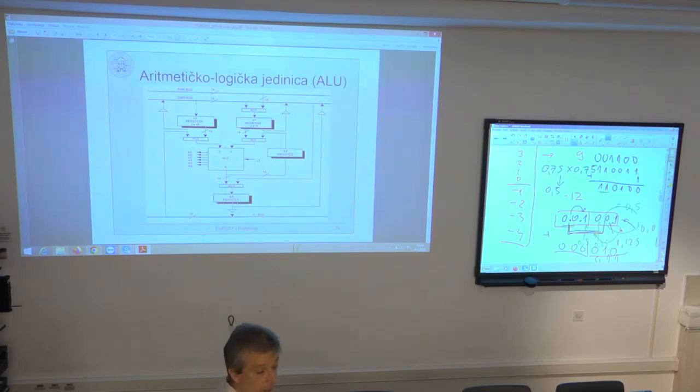So when you have the stack, another interrupt can interrupt the current interrupt service routine that is being processed, like a nesting of the interrupt requests. This cannot occur here because you only have one set of shadowing registers. So immediately, as you enter the interrupt service routine, you have to disable further interrupts from occurring, service the interrupt, and later release the registers back to the original values.